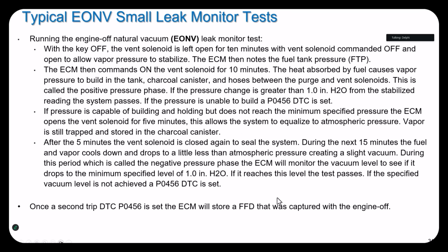And here's some more information on codes, but there's our 1 inch of water column. If we can get 1 inch of water column or higher, that means that system's got enough pressure to test, and we can work from there. If it's too high, it's going to suspend it and let it cool, check it again, check it again, check it again. That's why we need a good battery, and that's why it can take time to do it.